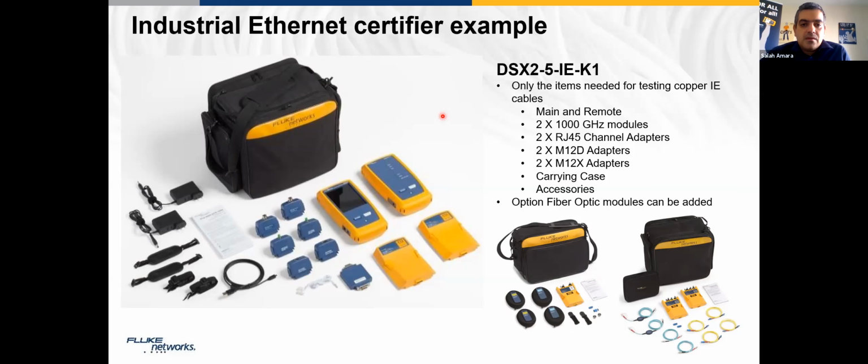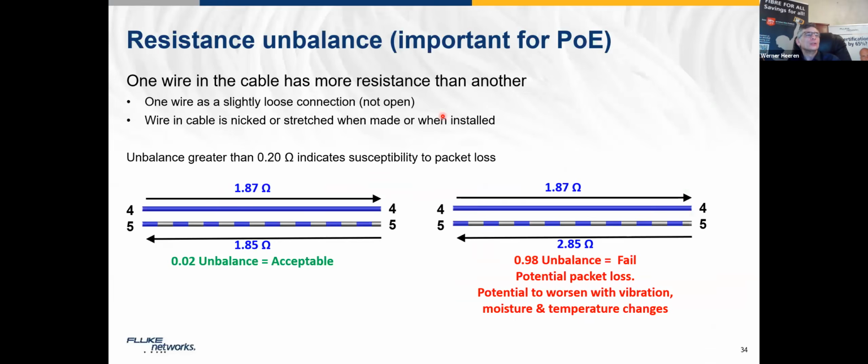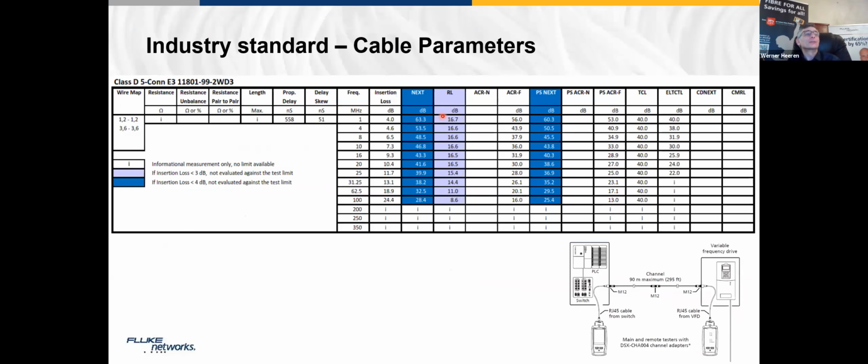Another question: is there any standard range for acceptable NEXT headroom? I think they mean, are the limits different from commercial? Yes and no. Some parts are the same, but remember the MICE parameters, there could be some differences on the limits for some parameters.